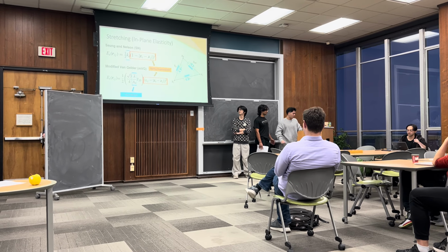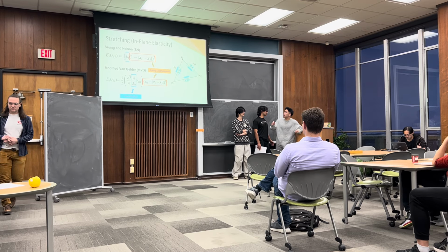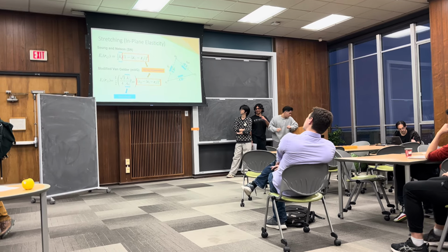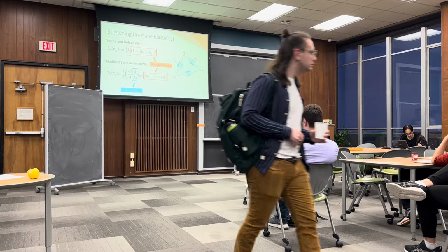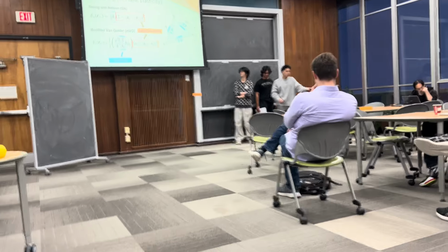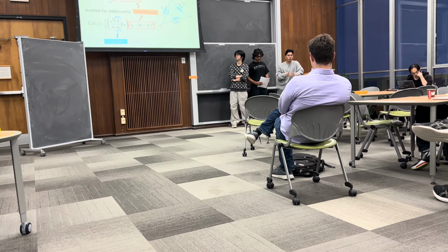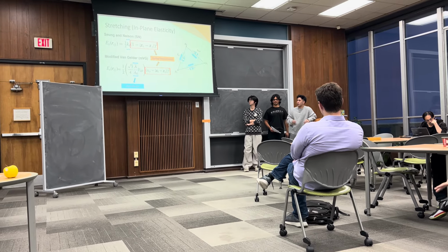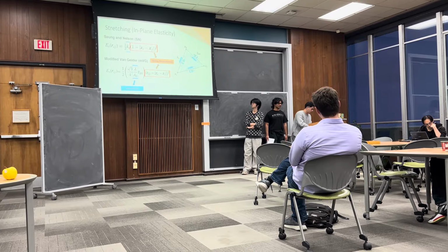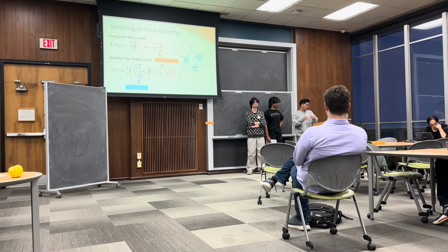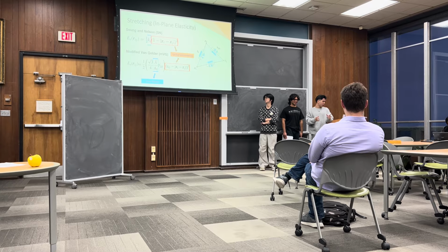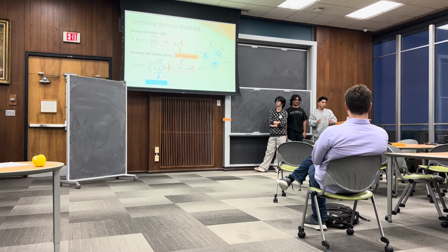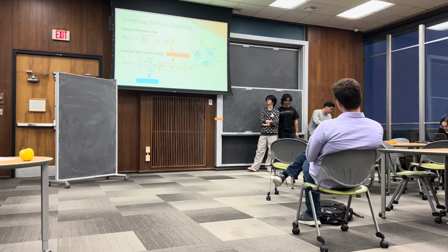And secondly, we can see that in the Zhan and Nelson model, Ks right here is a constant, and in the modified Van Gelder model, they use the weighted area to modify the energy, where A bar is the ideal equilateral triangle area, and A naught is the current area of the triangle. And as we can see, if there's any displacement for simple stretching, we apply forces to the spring, which is the edge. And if there's any compression, we also apply forces to the edge.